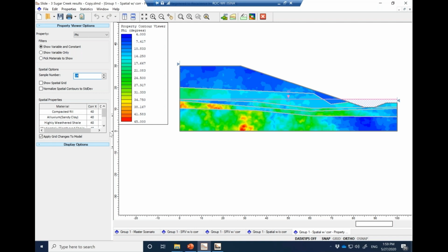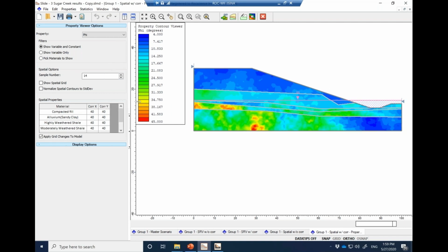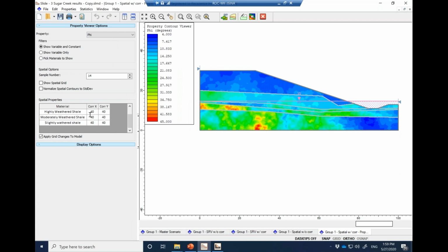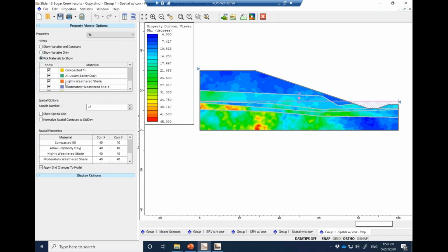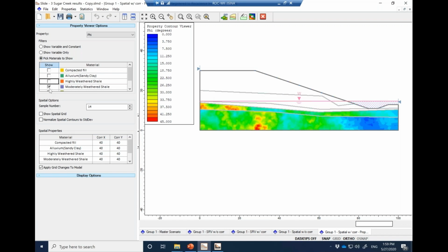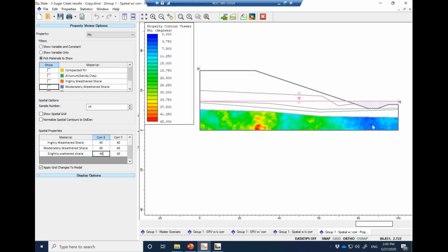The other thing here is all horizontal and vertical correlation length parameters are defined for all of our material. Let's say I want to select the material at the bottom of this model, and I look at this material and I see that, yeah, this is not my field, so let's change it. The recommended change is, for horizontal, we have larger correlation lengths compared to vertical. So vertical is 1, horizontal is 100.